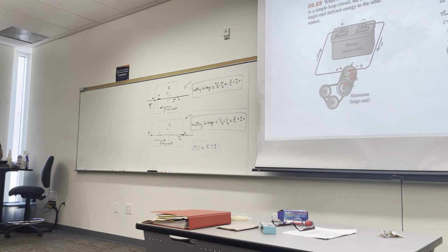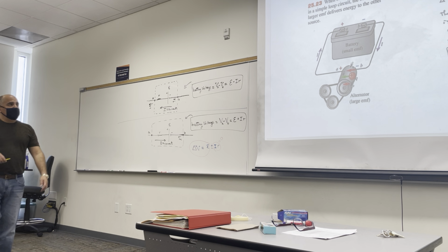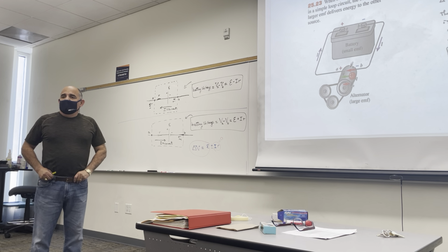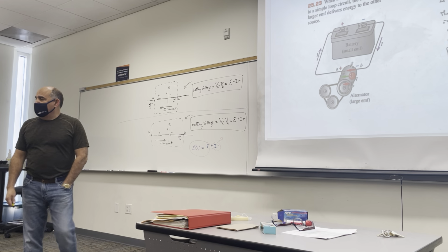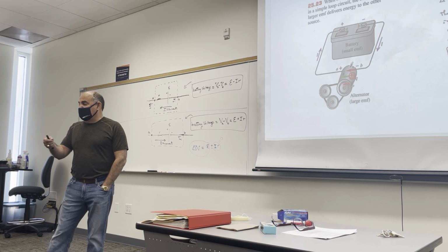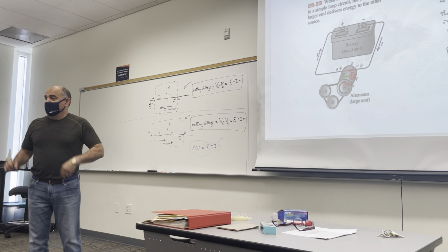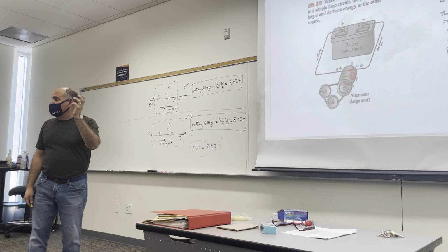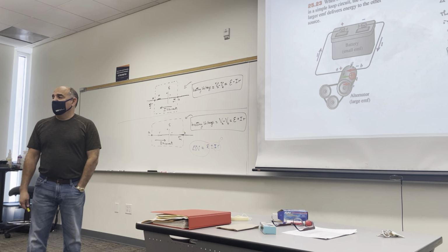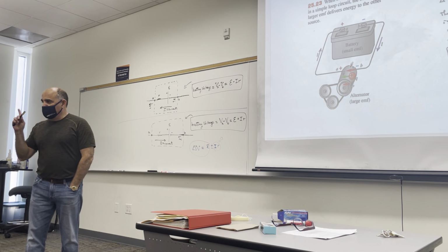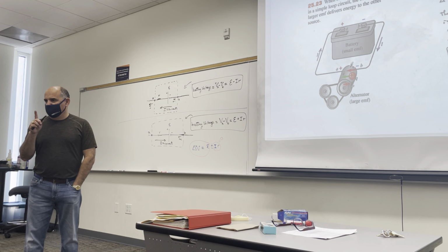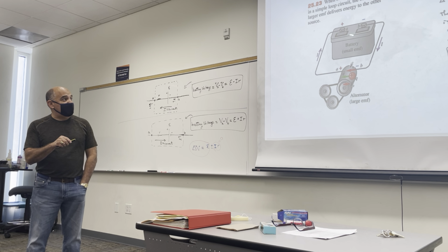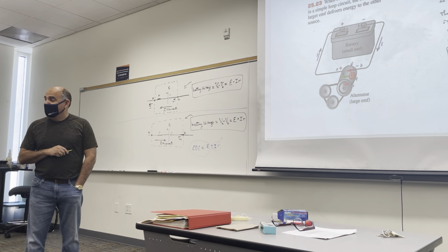By the way, just so you know, this is your car battery. Suppose you one day want to start your car, right? The engine, and it just goes click, click, click, and the battery's dead, right? And so you call AAA, and they come in and want to sell you a battery. You tell them first, before you purchase that battery, check the alternator. Because it could be that the battery is not charging because the alternator is the one that's bad.